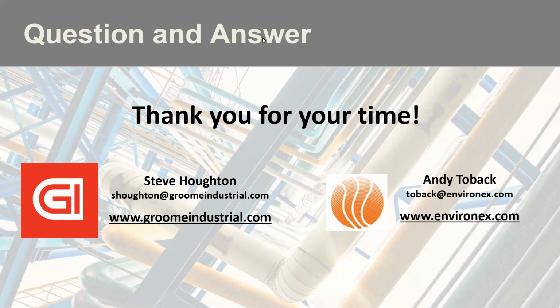Right. And this one kind of goes in line with that, asking about the tuning process. Is there anything that you can do to adjust ammonia flow laterally across the ammonia lance? That's a tough one. We've done that work, but it's not online. In cases where the problem is across the tuning zone, we had to re-engineer the lance or go in and split the lance.